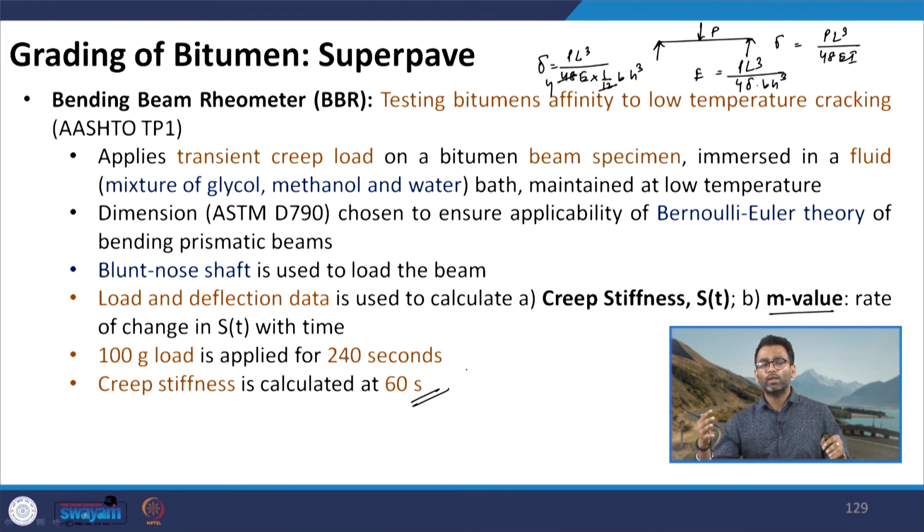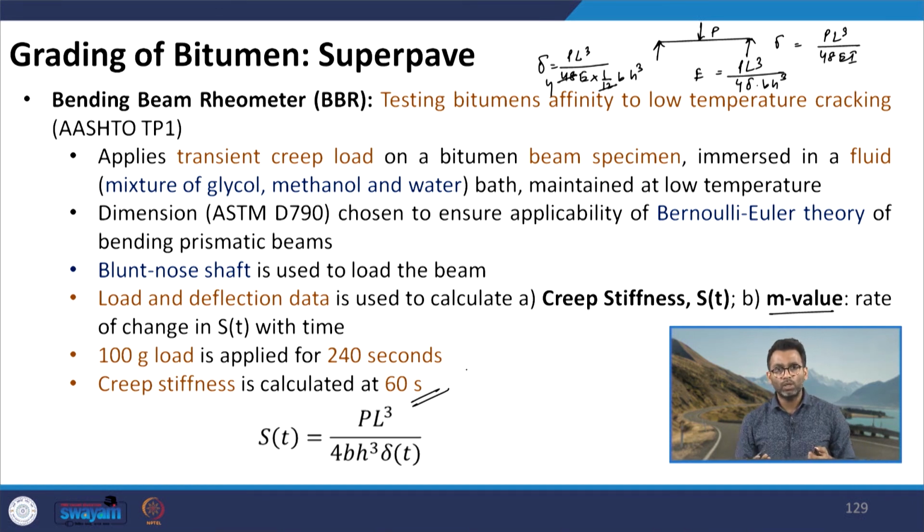Initially, when they wanted to correlate the thermal cracking with the stiffness value, the literature says you have to carry out the test for a very long period of time, and the value you are targeting is after 2 hours. But you can understand that 2 hours is a very long duration for the test. So in order to reduce the timing of the test, they used the time temperature superposition principle. If the target temperature is minus 22 degrees Celsius, you actually do the test at 10 degrees Celsius higher, so at minus 12 degrees Celsius.